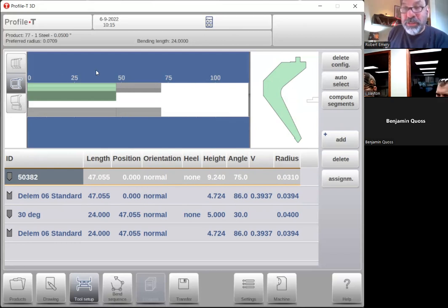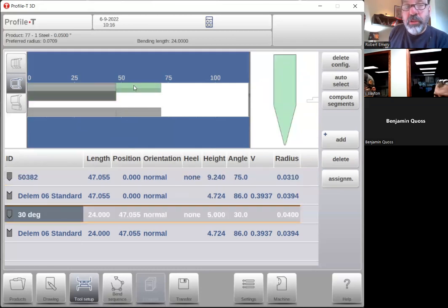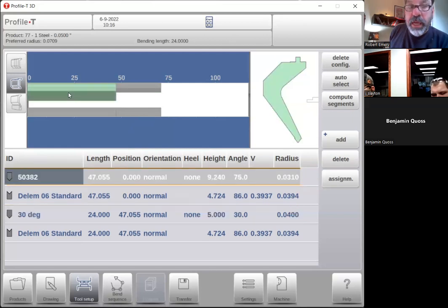We can't beat the physics. If these tool heights work together though, in these pairs, this would be a legitimate thing to do. But this punch is tremendously longer than this one. This was crashed well before this ever got to do any work. I can't beat the physics, but you can definitely add multiple tools.